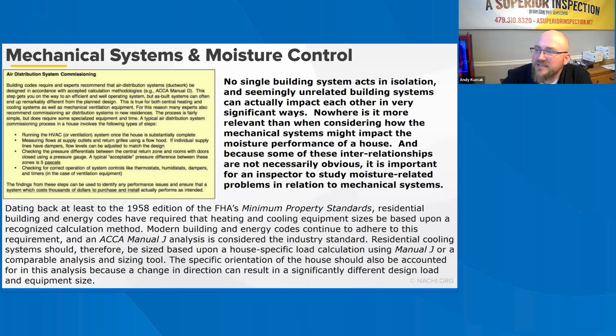Building codes require that joints in duct systems be made substantially airtight by means of tapes, mastics, gaskets, and other approved methods. This guide recommends sealing duct systems such that air leakage to the outside of the building envelope is less than or equal to 5 cubic feet per minute at 25 pascals per 100 square feet of floor area